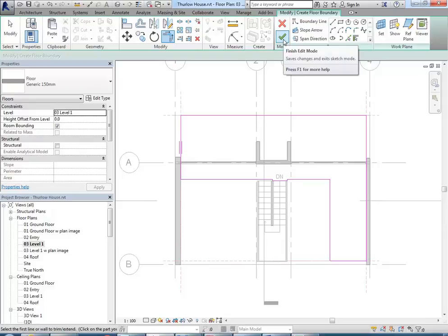Well, I think you've actually got an extra one over the top of that on the other side. So just undo, and then delete the other one instead, the one going to the left. Delete that, and you must have an extra line somewhere there. Oh yeah, I can see it on the left. That one there. Now try trimming and joining that, or just drawing a new one. Oh, there we go. Now try finishing it. That should be right. There we go.